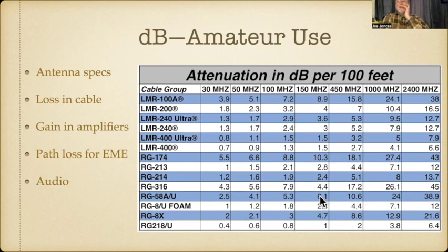Yeah, okay. And it depends. If you're in an area where you're only 5 miles from the repeater and you have a direct line of sight, you could use 200 feet of RG58, which would be a 12 dB loss, and it wouldn't make any difference because you're right there and you can get the signal.